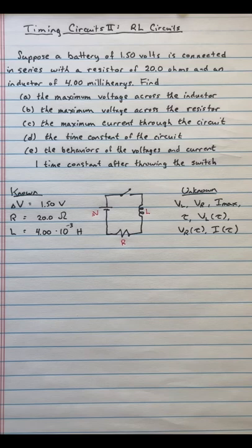Now, because this isn't storing any charge, charges are going to be moving once we close the switch. There's no charge, for example, stored on anything at the moment in any real sense. We'll have current flowing through it. Again, I'm going to let your lecture instructors talk about why this works this way, but because of the way that coils work and because of how Faraday's law works, specifically the negative sign in Faraday's law, the current through the coil will not start at a maximum. It'll start at 0 and build up to a maximum.